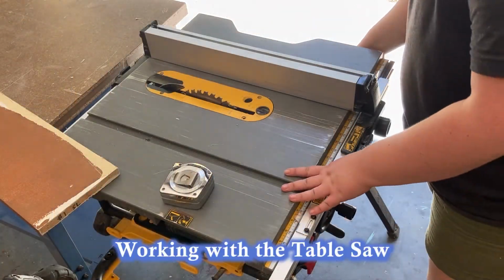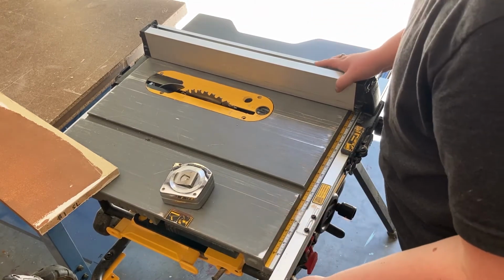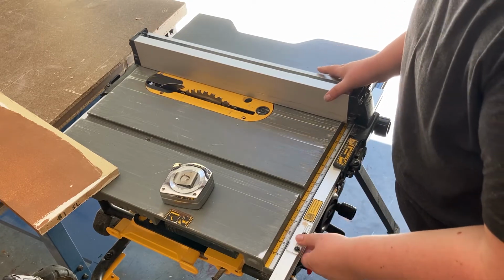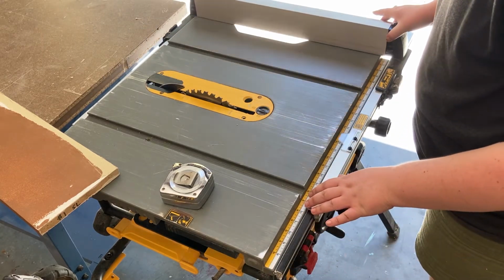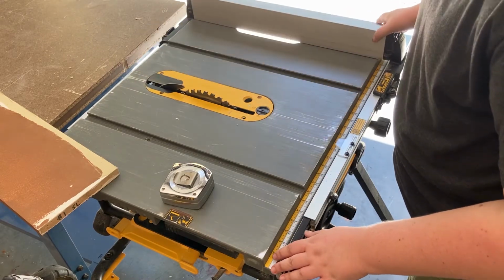So I want to set this saw up to cut the 1x3. There's a release over on this side, and you may see, I don't know if you can see in the camera, but there is a ruler set along this edge, and this guide is able to slide into different positions so you can set your distance from the blade.